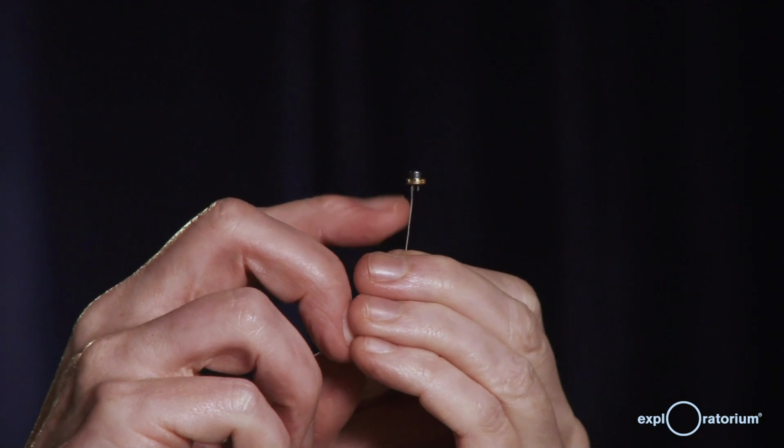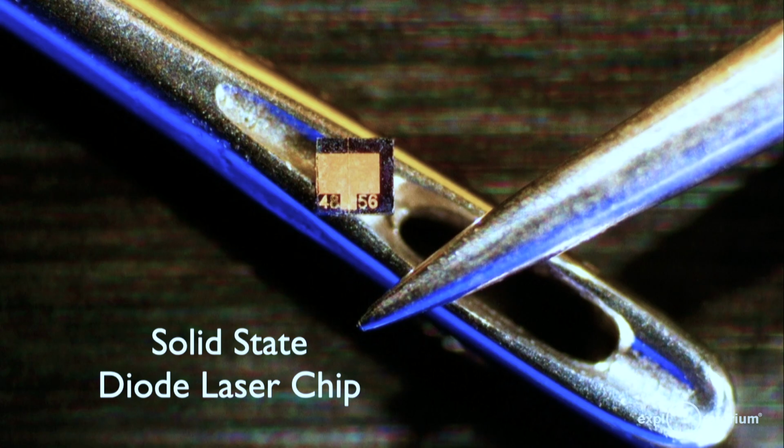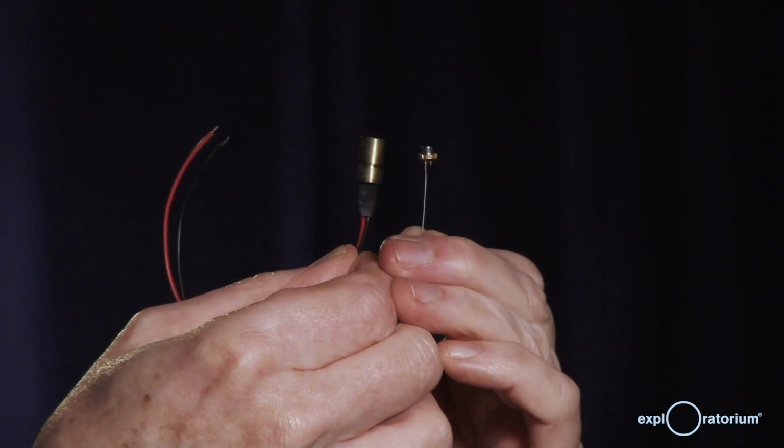I'll show you what the laser diode looks like. And it's very small. I mean, here you see it in comparison to a penny. So this is a very, very small package. Inside of that package, there is a little chip. It's actually kind of like an LED. You apply electricity to both sides of the LED, it glows, except this chip inside of here is polished on both ends. The light bounces back and forth and gets amplified and comes out one end of the chip and then comes out of a little window at the end here. Now this is actually pretty small too. This is actually packaged inside one of these, which is inside one of your laser pointers.